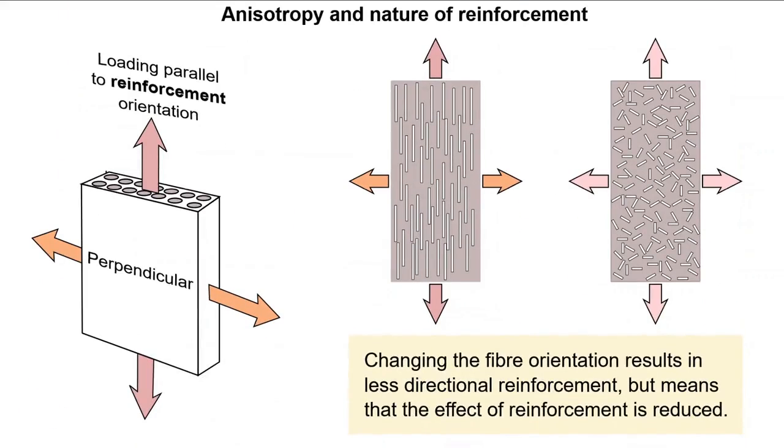Specific to fiber reinforcement, long continuous fibers demonstrate the highest degree of anisotropy. If the fibers are randomly oriented, and by virtue necessitating being shorter in order to fit, then anisotropy will be diminished. The fibers are less effective at establishing anisotropy on the basis of orientation. However, this is at the disbenefit of overall beneficial magnitude in any given direction. This is largely down to the effect of fiber length. Let's now examine why.